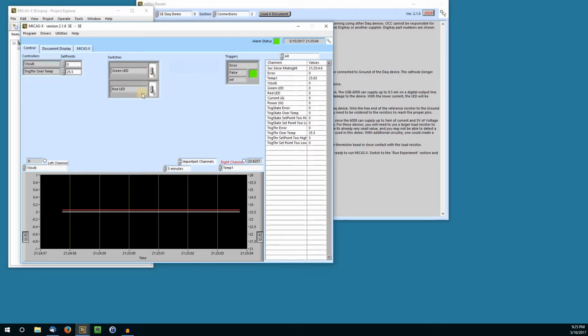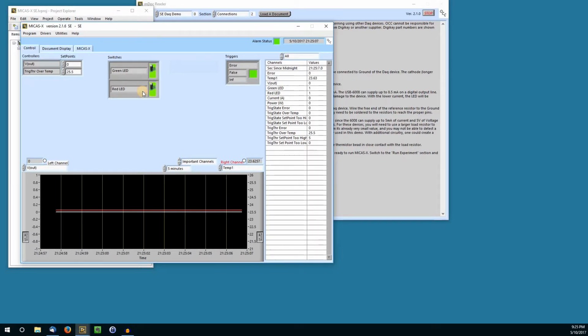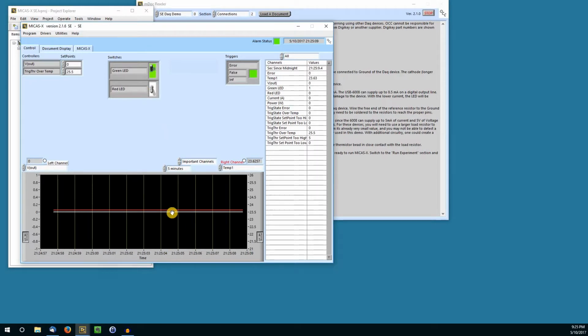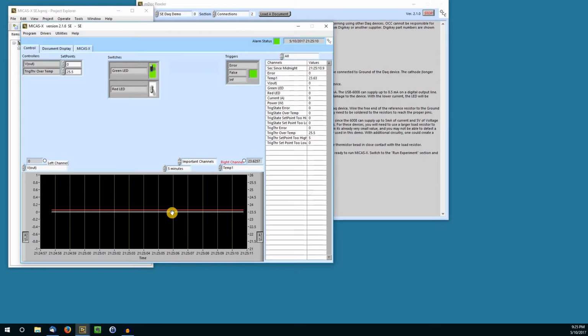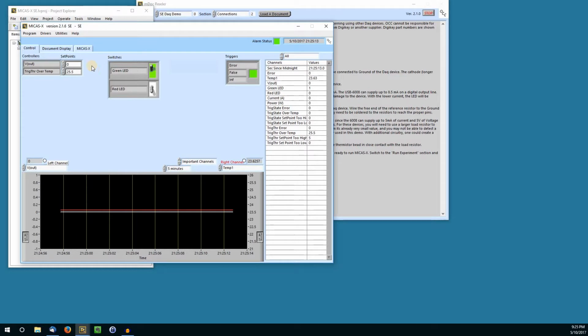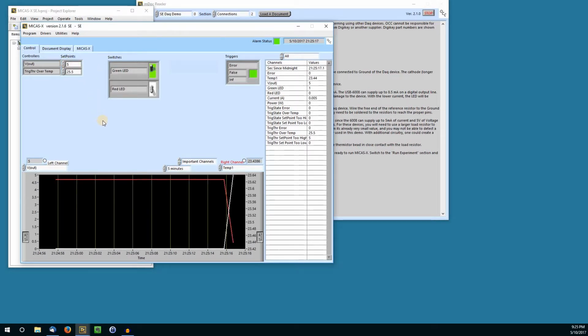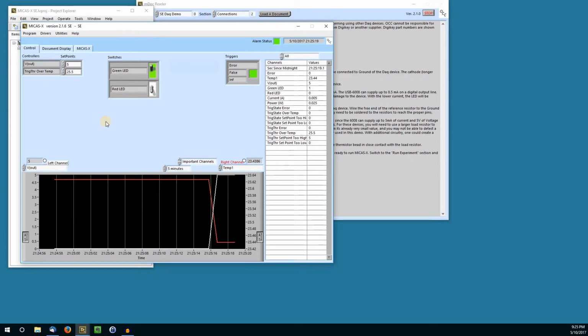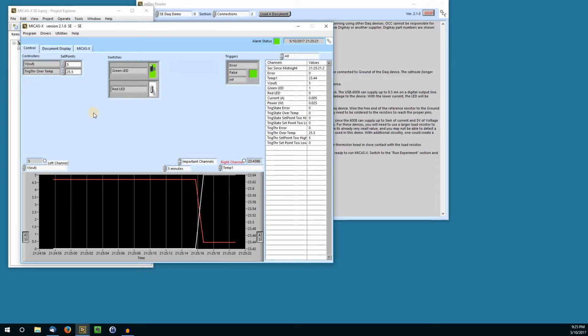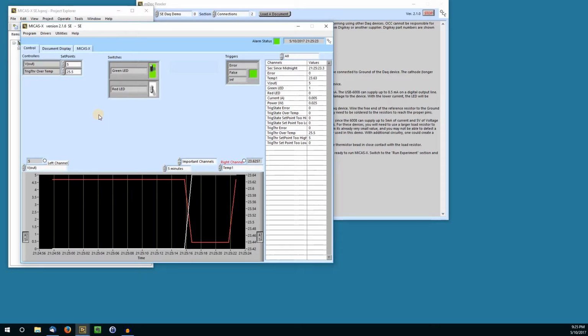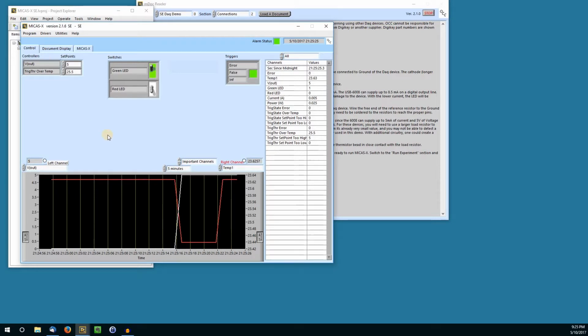The graph at the bottom shows the time evolution of the voltage out and the measured temperature. After the program has acquired a background temperature level, change the output voltage to 5 volts. As the load resistor heats up, the thermistor will gradually read a higher temperature. With this system, we can see about 1 degree Celsius of temperature rise before the temperature levels off.